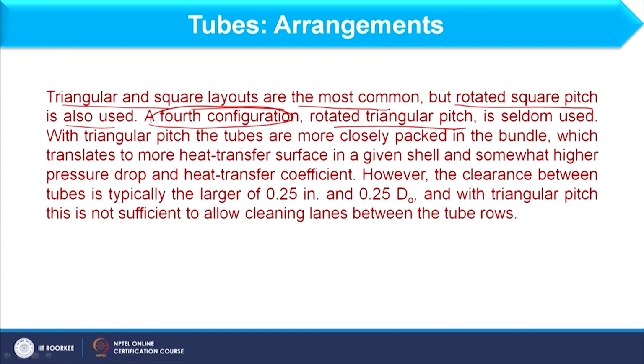So, with triangular pitch the tubes are more closely packed in a bundle, which translates to more heat transfer in a given shell, and somewhat higher pressure drop and high heat transfer coefficient. So, you can understand that triangular pitch is more compact, it gives more heat transfer coefficient and more pressure drop, right.